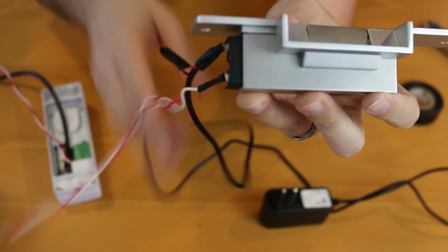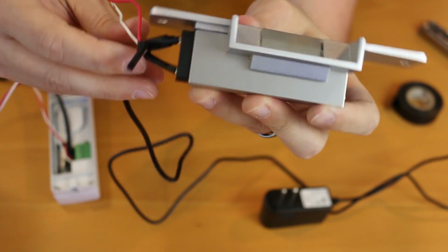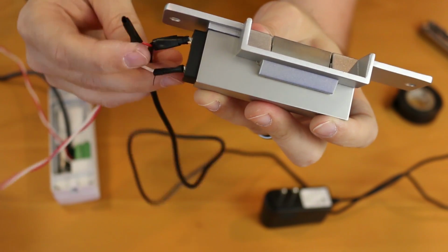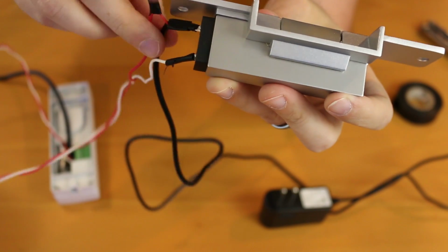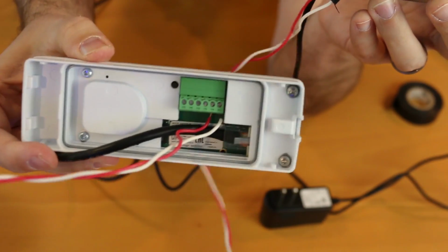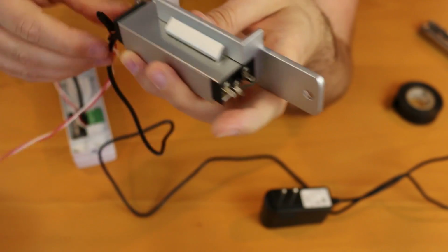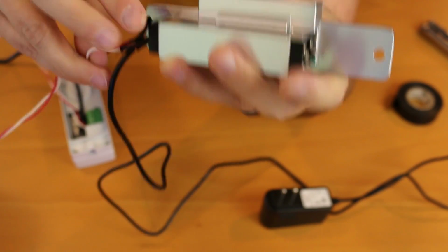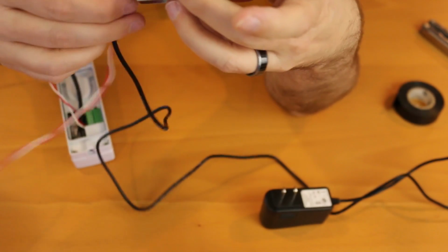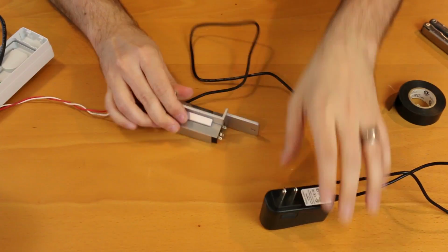So again, the power cable is this black cable. Power splits into 2. Black power cable goes to the door strike. Red power cable is spliced in with the red doorbell wire. The red doorbell wire goes into one of the contacts here, and then it comes out of the white wire. And the white wire is now connected to the other side of my door strike right here. Okay, so I've got it all taped up, so it's a little difficult to see, but you get the idea, hopefully. And now we're gonna power everything on.